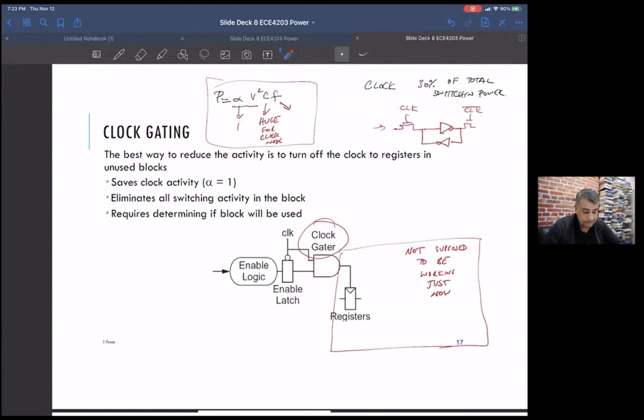For example, if you don't delay the enable logic or make it synchronous to your clock or to the inverse edge of your clock, you could easily, if this was a synchronous enable or disable, get a situation where you get some extra clocks clocking your registers, and you could put your circuit into an unknown state before you go into shutdown or when you come out of shutdown.